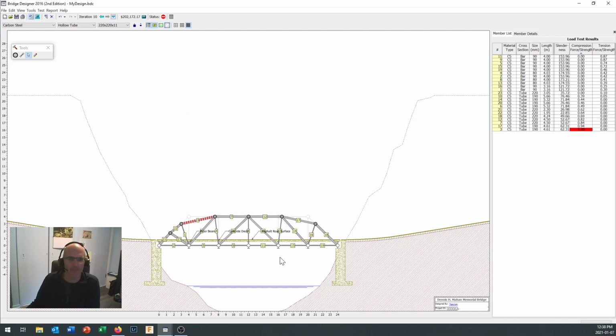Alrighty. You guys have slightly different bridge configuration. You've got one more node in there to deal with. I went with the easy one here, but as you can see, it didn't take long to knock $70,000 off the price of the bridge. Some of you guys have already gone through and done the easy things, so you might want to start experimenting with setting your grid to the fine grid so you can move things about a little bit on here.